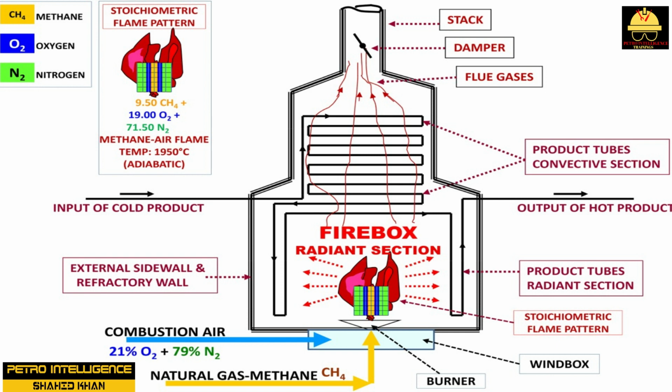damaged header box gaskets. Ensuring proper air concentrations is critical to efficient furnace operation because the fuel burns cleaner and hotter. Incomplete combustion reduces heat output, produces waste gases, and creates a potentially hazardous condition as unburned fuel collects in the firebox. Safe, efficient furnace operation requires an operator to closely monitor and control the combustion process.